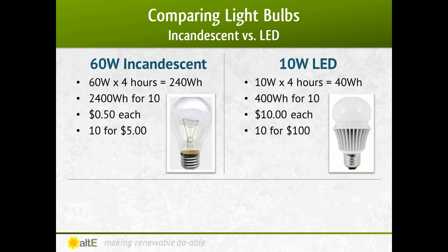You've all been hearing for years about swapping out your old incandescent light bulbs. A lot of people didn't like the CFL bulbs that were the only alternative at the time. These days, LEDs have come a long way, baby. Let's compare using 60-watt incandescent bulbs with 10-watt LEDs. Granted, LED bulbs cost at least 20 times more than an incandescent bulb, but stick with me. I'm going to show you how it makes sense to swap to an LED bulb next time your incandescent goes out. Both bulbs put out the same amount of light, both are dimmable, immediate on, and work in the cold.